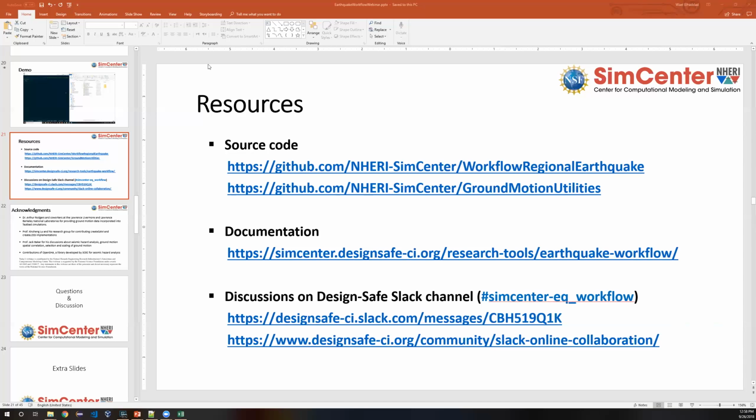So if someone is interested in visualizing results similar to the way we did in the testbed, there is a small guide on how to do this in QGIS, step by step: where to get building footprints, how to import them in GIS tools, how to import the results from the SimCenter regional simulation, and how to join the layers to be able to do a parcel level visualization.